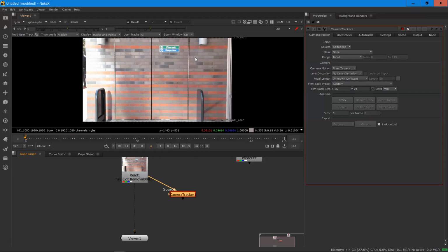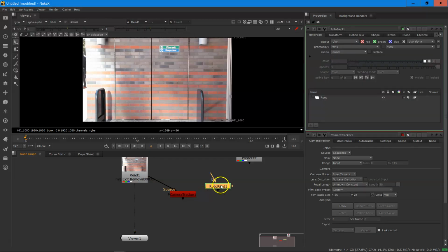So that can mean that if you have somebody, say, walking around in the scene, so you've got a person or you've got some other kind of object that is moving by itself that has nothing to do with the camera, the track wouldn't work, because obviously the software will assume that movement is related to the camera's movement. And so we have to make sure that the camera tracker is only used on objects here that aren't moving. I have noticed there's a person on the side of the screen, but hopefully they won't make an issue in this case. But I should just point that out, like I said. So it's not that you can't use a camera tracker on a scene with a person, but you just need to mask them out. So what we would generally do is just use our rotopaint, just like anything else, and just draw around the areas we either want to remove or keep, depending on the settings we use.